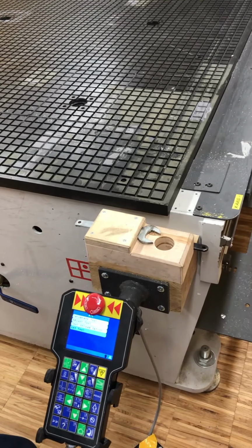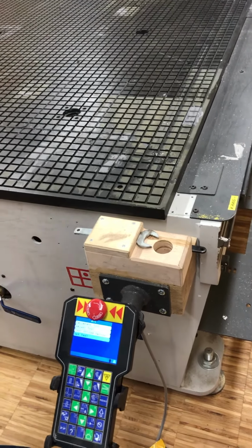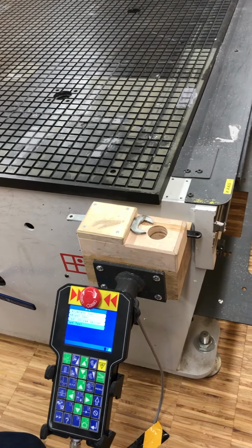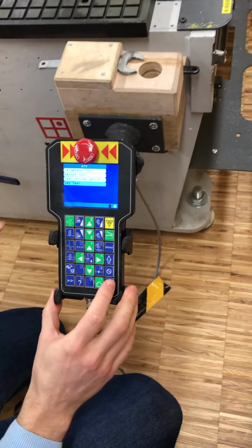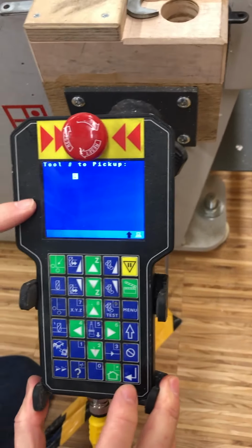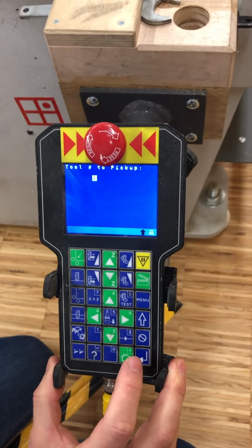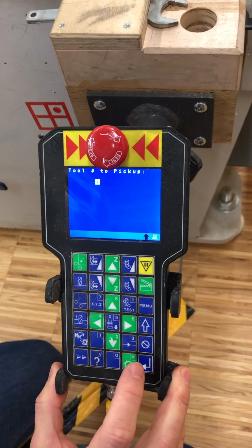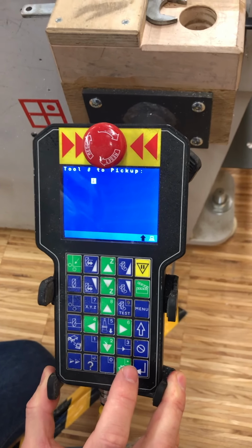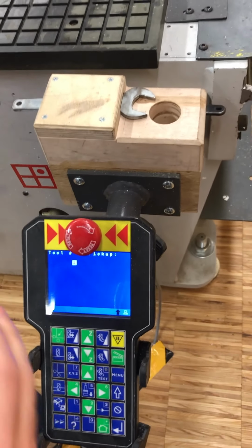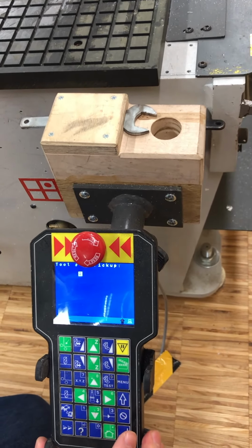If we would make the mistake, that's a grave mistake, of putting a tool in number 1, it doesn't know, of course, it's not aware of that. So we will have to get another tool, and then we can get the number 3, because then it will leave number 1 in the tool holder number 1, which we then can exchange, while it has number 3 in the holder.